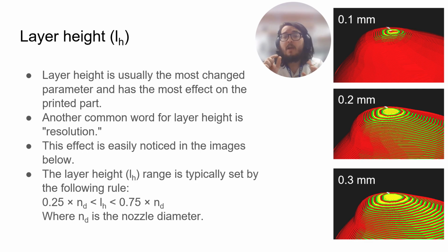And that's also why people sometimes refer to higher nozzle diameters as fast nozzles or faster printing, or sometimes draft type print nozzles, like a 0.6 or a 0.8. If we follow the 75% rule, a 0.8 will have a 0.6 millimeter layer. So it's going to be 6 times faster than a 0.1.